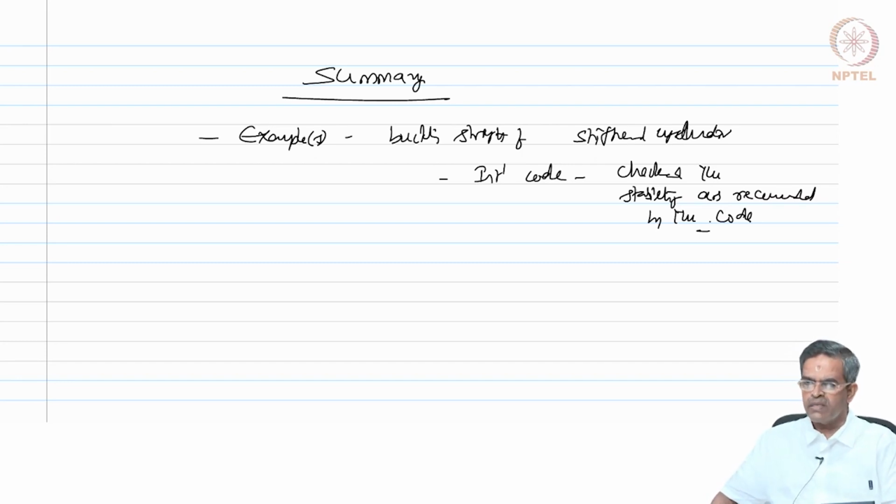Once you have this matrix, we formulated the characteristic equation where we set the KUU determinant to 0 for a non-trivial solution. We used either stability charts or stability tables available in the literature to choose the psi value, the phi value, which is the ratio between the axial force and the Euler's critical load.